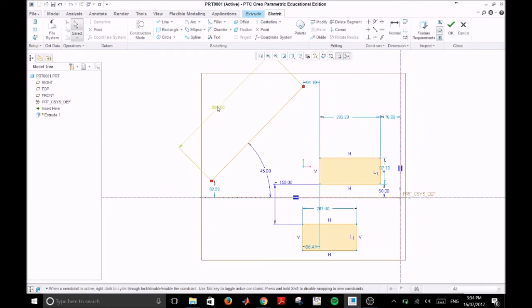These dimensions can also be moved for clarity, so you can move those away or closer. This can be useful for more complex models when dimensions can get in the way of one another. But once again, it's worth spending some time having a bit of a play in the sketching dialog box and practice locating dimensions using the normal tool.